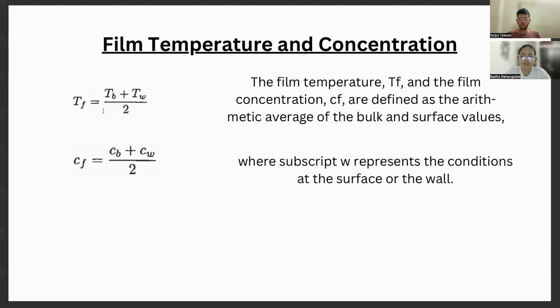And concentration Cf is Cb plus Cw by 2, in which Cb is the concentration at the bulk and Cw is the concentration at the wall. So basically, these are the film temperature and concentration and bulk temperature and concentration. You will use this further in the engineering correlations.